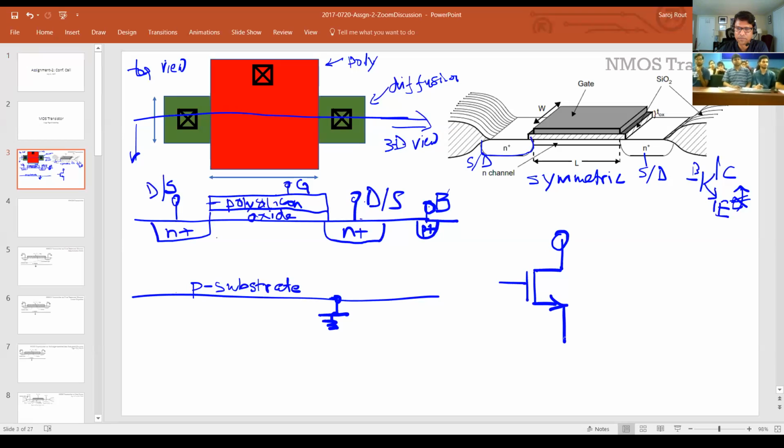Now, usually when you bring the symbol in Cadence, for example, that's obviously your gate, and this symbol tells you that if it is an N channel and this is your arrow, this is usually the source and this is the drain. But that doesn't mean that it is drain and source. It actually depends on how you bias it. Then usually the bulk is annotated by putting a middle connection. A lot of times when we're doing circuits, we would just omit this for clarity. That usually means it's connected to ground or the lowest supply, or connected to the source terminal.